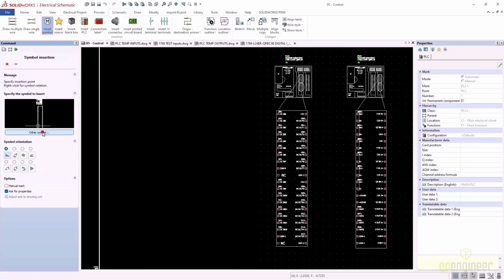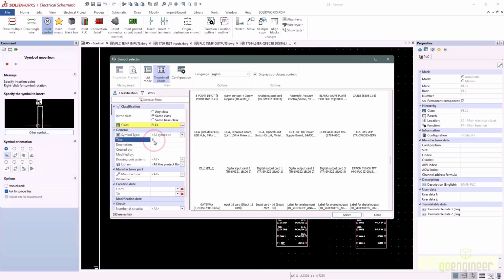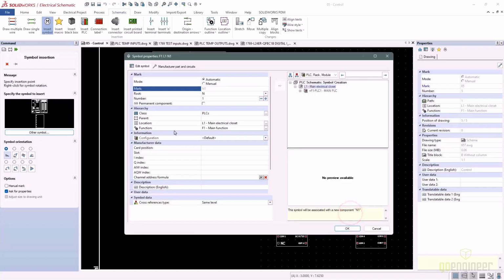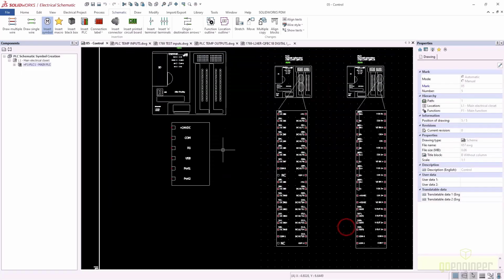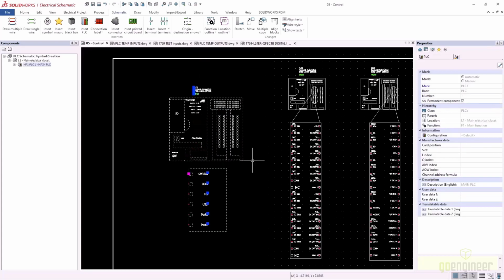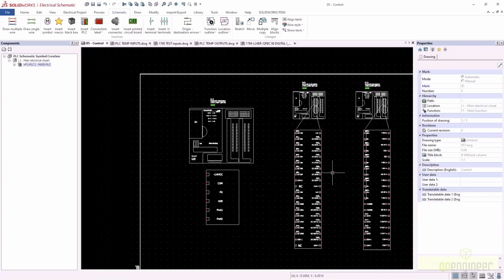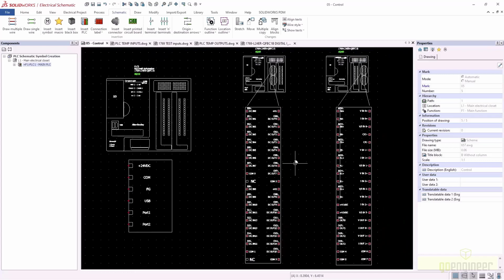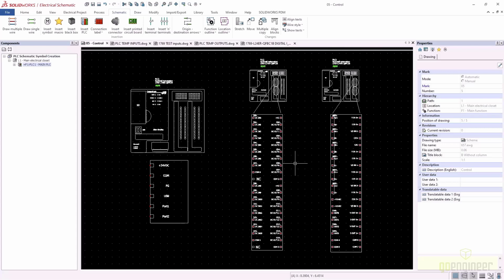Let's look at what I created here for my last power symbol. That power symbol, I got rid of the ellipses, just cleaned it up a little bit, made it a little larger, so that it showed a little bit better. Here's what that looks like now. I also changed the cross-reference text to be green. I did add one extra attribute to show those different pieces.